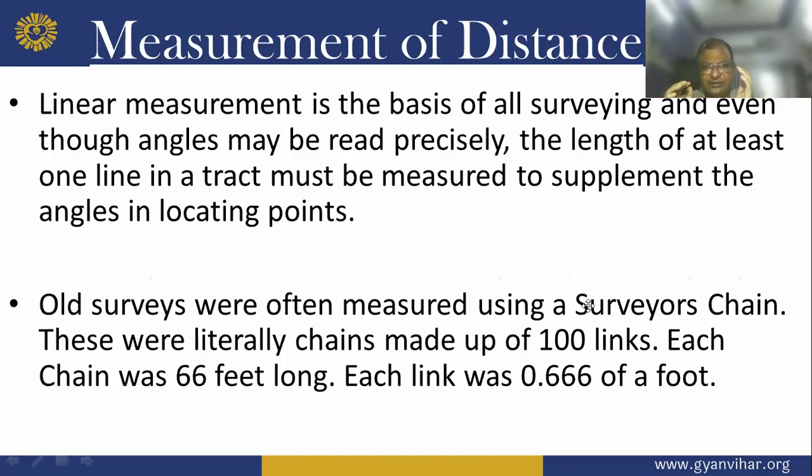Now, linear measurement is the basis of surveying, and even though angles may be read previously, the length of at least one line in the tract must be measured to supplement the angles.